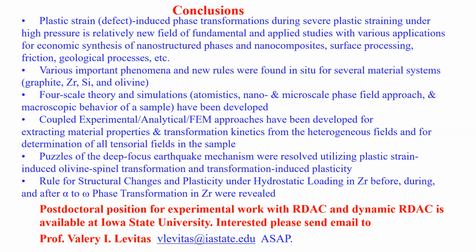Well, I assume that it will be different, because in shock you do have plastic deformation, but not severe plastic deformation, unless you have shear banding. If you have shear banding, I don't expect any difference. But time appears as a parameter. I did not discuss one of the slides, actually, but even in more detailed experiments, time also appears as a parameter. If after torsion or after compression we keep the sample without additional compression and measure the time evolution, which nobody did before, it progresses, so the volume fraction increases by 20 to 30%. So actually, even in our case, time should be included. We will work on this.